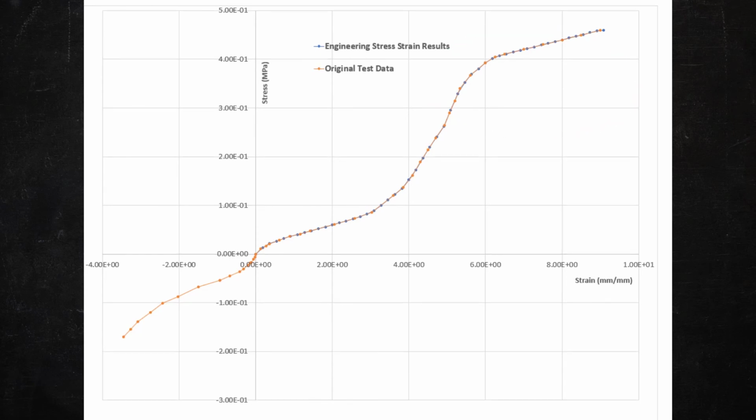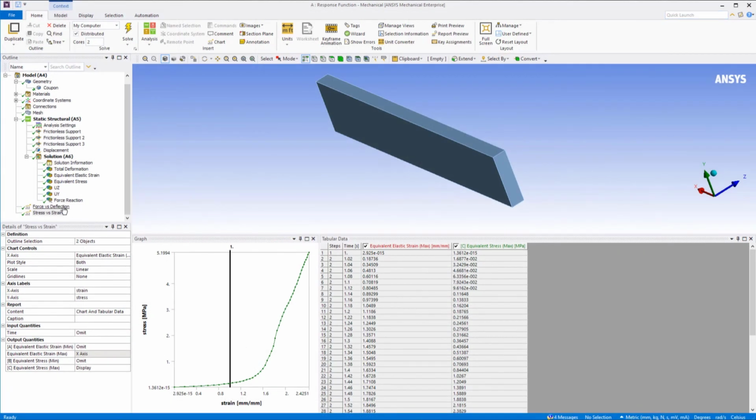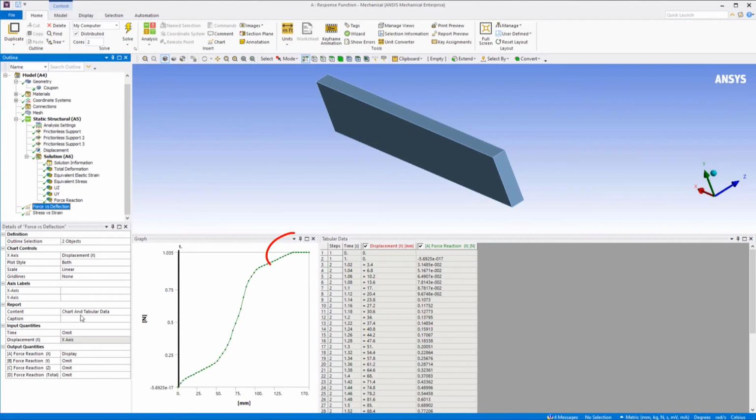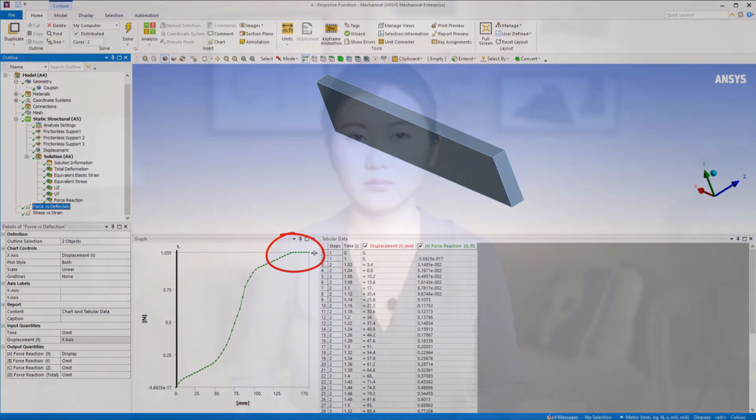It is worth mentioning that once the loading exceeds the original experimental data, we can expect the force deflection curve to become a flat line. Hyperelastic materials are intended to represent a class of materials that exhibit highly nonlinear behavior with large deflection and different responses in different modes of loading.